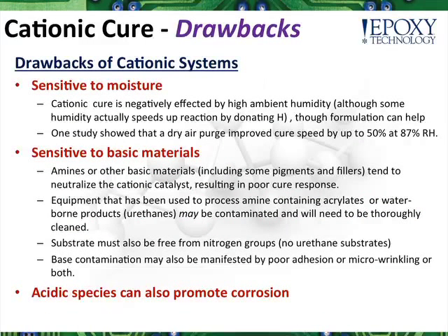But it's absolutely possible and only possible with cationic systems. Cationic UVs do have some drawbacks. For example, they are sensitive to moisture. Too much moisture in the environment can absolutely negatively affect your cure quality. And we've actually seen that dry air purging can substantially increase cure speeds.